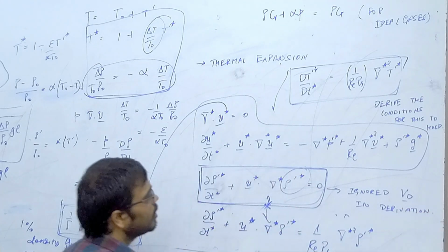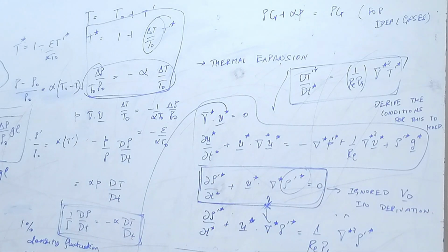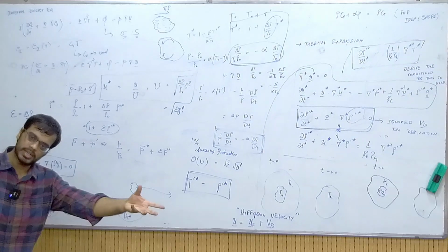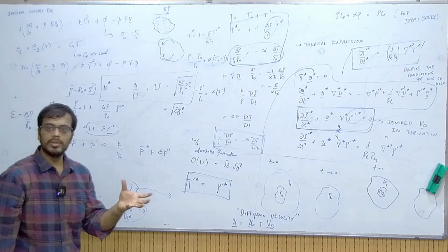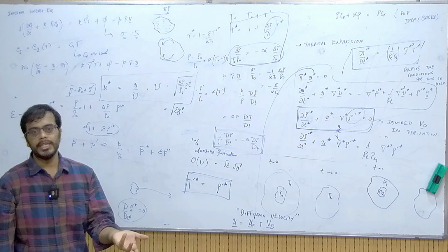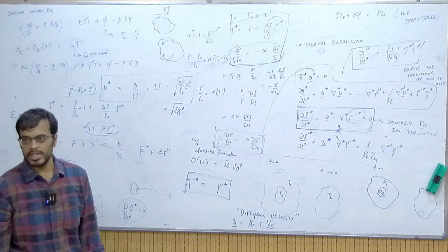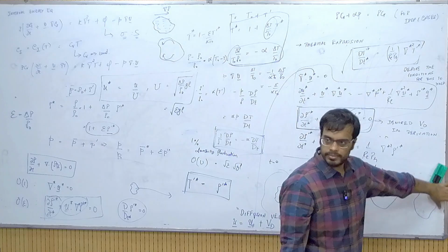That diffusion velocity is important because it helps in reconciling these two equations, and it captures a very important physical concept: when you have density diffusing, you do have a velocity of the center of mass, which is what your u has been everywhere. This u has been the velocity of the center of mass, not necessarily the translational velocity of the fluid particle. A fluid particle may have no translation, but yet its center of mass might be shifting due to changes in density, diffusion in density.